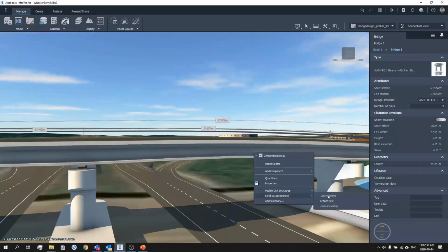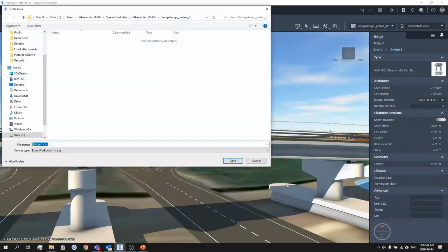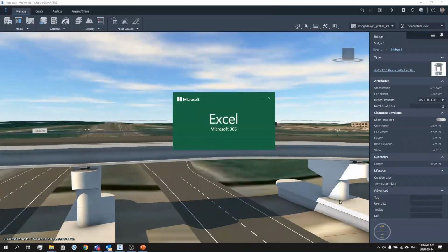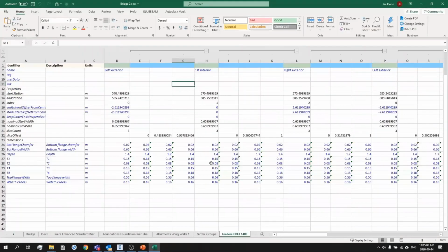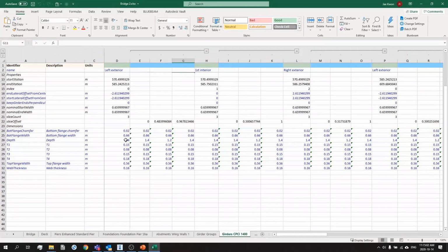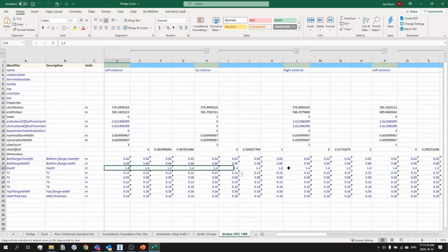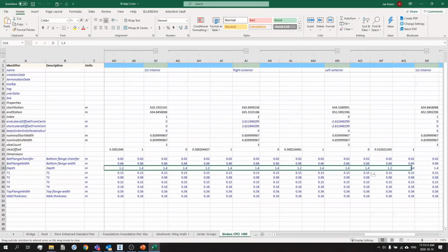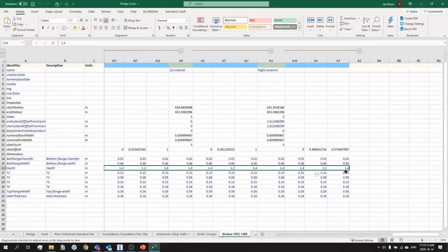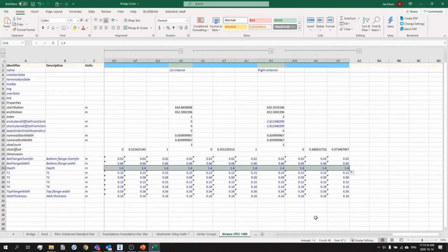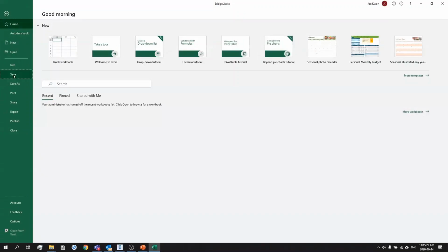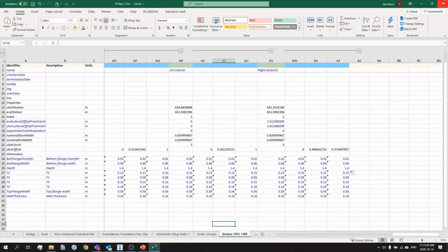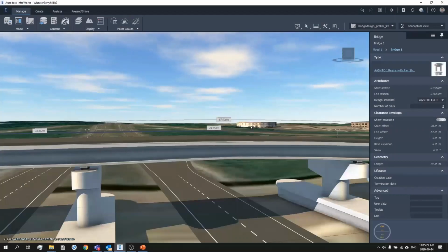So there are a lot of parameters to edit. You can actually send it out to Excel to edit those parameters. Each component group sort of has its own tab or worksheet, and any of the blue values you can change, mostly as a rule of thumb. And you can use autofill features. I mean, just it being in Excel opens up all sorts of possibilities as far as linking them with formulas and things like that, just to make it easier to edit things in a group.